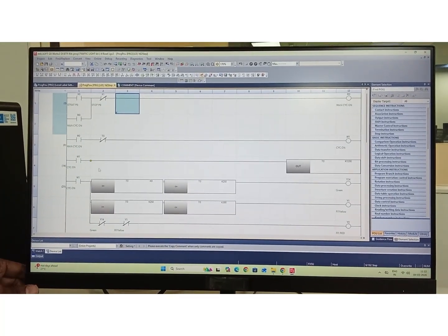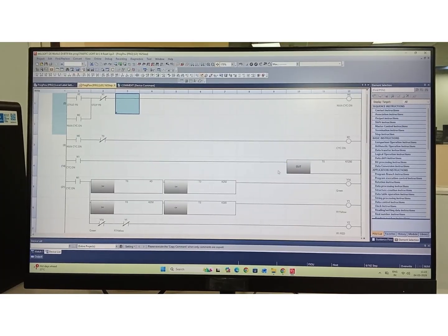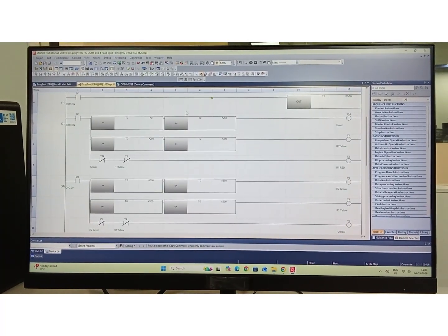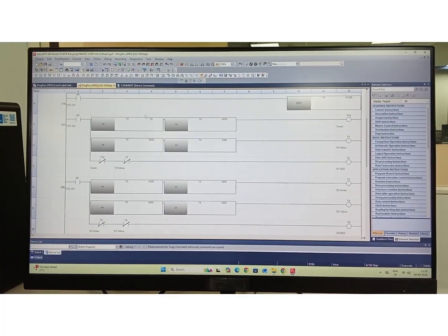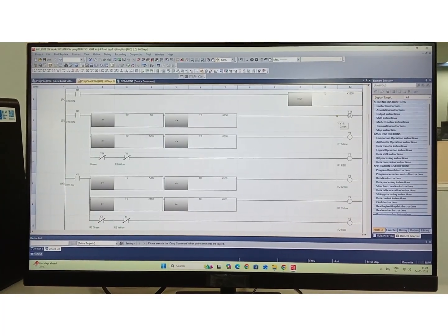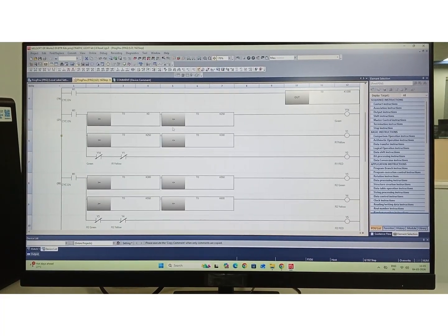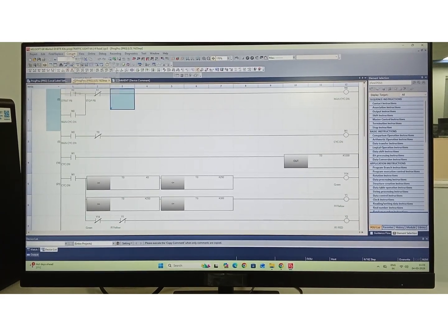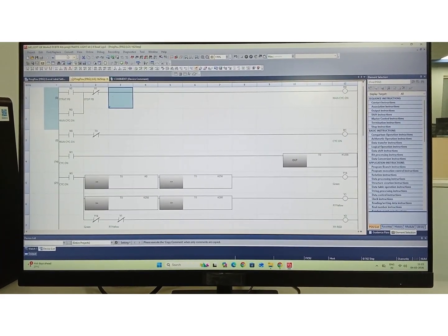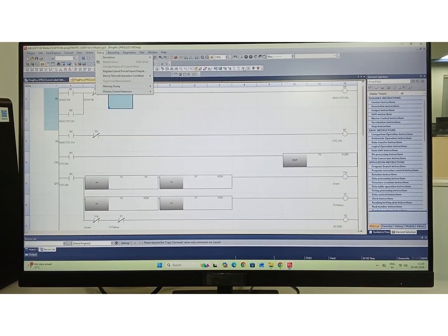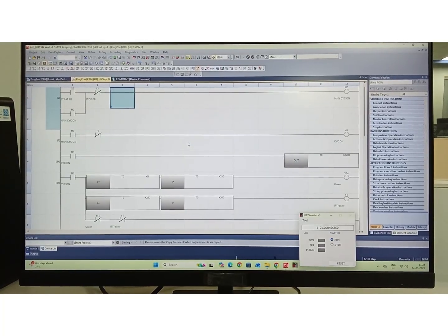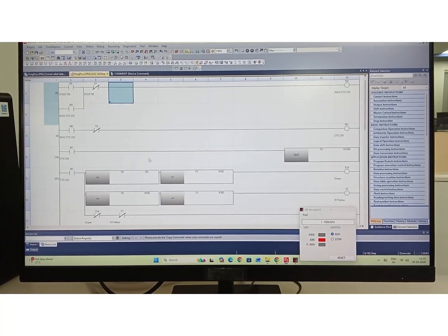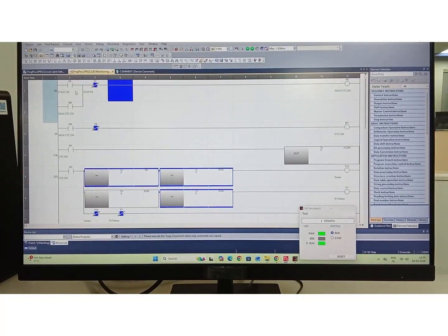Afterwards, when M1 is on, it triggers the timer and the timer starts counting from 1 to 120 seconds. While counting, we compare using arithmetic operations to give outputs like Y14, Y1, Y2, like that. First, once we write this, we need to convert. And once we have converted, next we go to the simulation. Yes, there is no error. It will directly take us to the simulation.